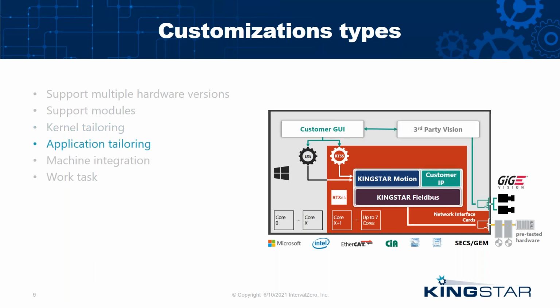Then on the non-real-time side, or at the application level, there will also be customization needs. Some features such as an inspection module or a calibration module will use their own standalone software or their own standalone library, which may be real-time, non-real-time, or on a dedicated board. The application must be able to adapt and use this software when those modules are added. This is done with either open protocols or open configuration files that are passed to the controller so that the controller can know which modules to load, where the modules are located, and what parameters to apply based on the customization. So this application needs to allow smooth communication between the different modules and between the different features.